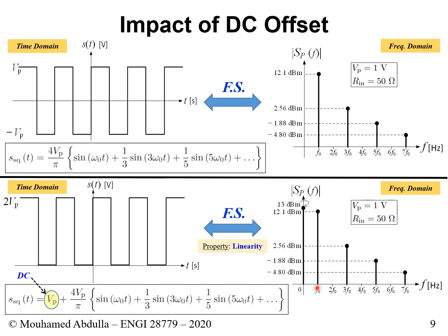And therefore, in the frequency domain, we simply add the spike for this. When you have a flat DC component, what happens to it in the frequency domain is just a spike of the power of this signal at frequency 0. That's frequency 0, right? So frequency 0 is where you have your DC component. And we put it here, and in fact, the value with the corresponding numbers is 13 dBm. This is what you get. This is your DC component here.